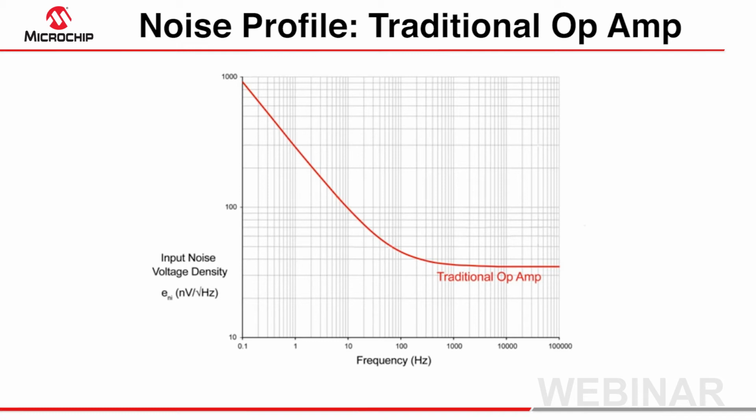So many sensor-based applications operate with high gains, maybe 100 volts per volt or even more, and at very low frequencies, typically below 10 hertz. Consequently, the 1/f noise is potentially the main cause of system performance restrictions. Standard methods of external high or low pass filtering to help attenuate the 1/f noise are not very practical.